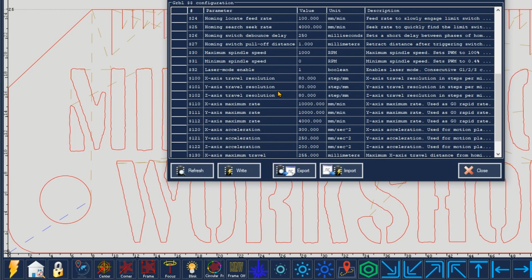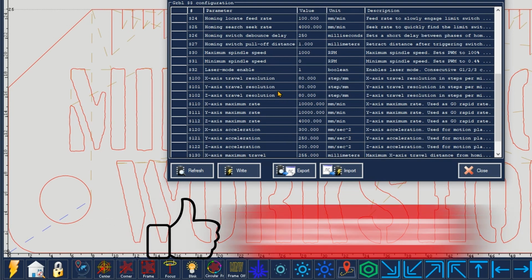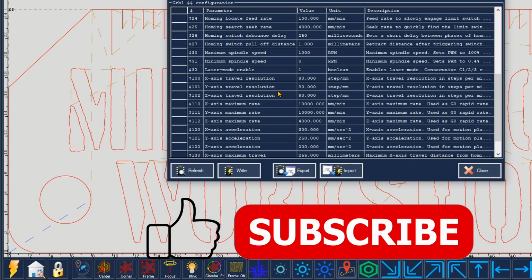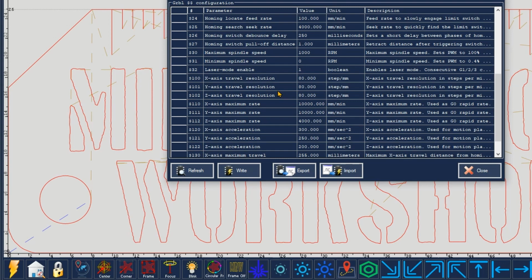Now, the electric motors driving the axes in your laser engraver, and also in many other CNC machines, are called stepper motors. They basically move in steps, so the board is sending impulses, and depending on how many impulses are sent, a certain number of steps are done.